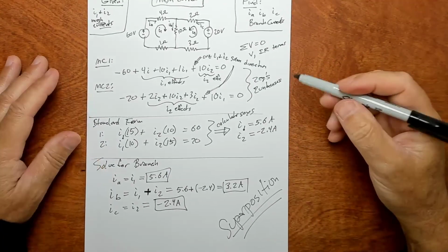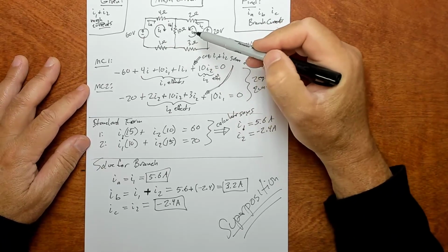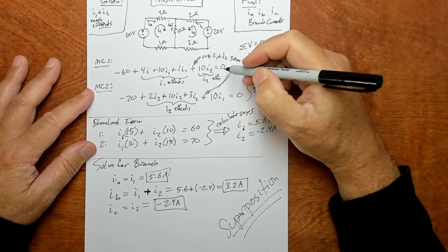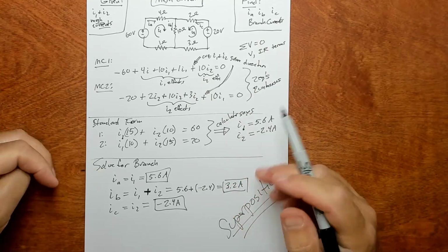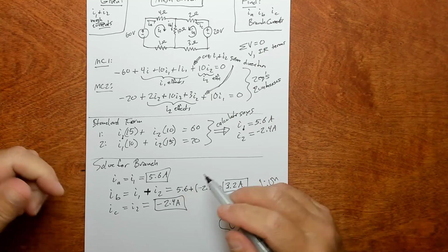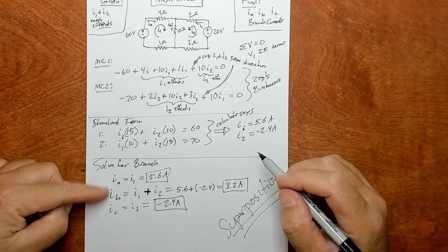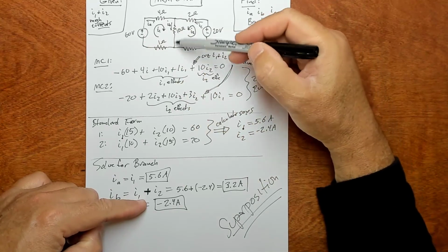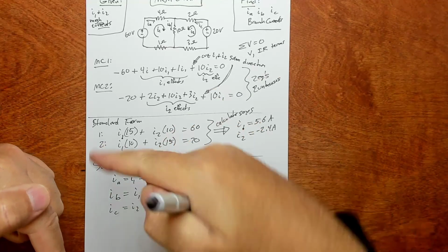Basic idea of which is you treat these mesh currents independently when you write the equations, and you add in the effects of the other mesh currents, but if you need the actual total physical current that's going through a particular branch, you need to reconcile the mesh and branch currents. Sometimes they're the same if that's the only thing happening. Sometimes it's the sum or the difference, if they agree or if they disagree.